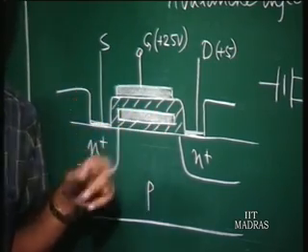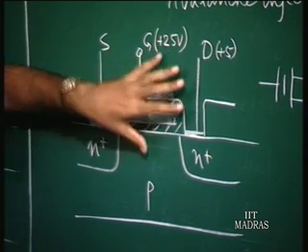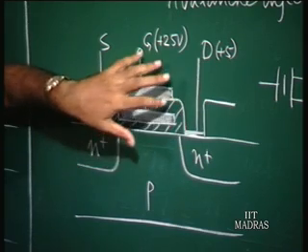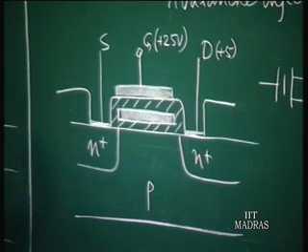Now, what is the effect of a negative charge on the floating gate? So, this is for programming, where you put a gate voltage of 25 volts and a drain voltage of 5 volts. For normal operation you will have normal voltages, say gate voltage 5 volts or so.